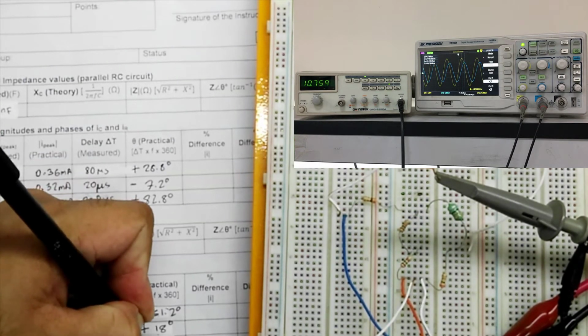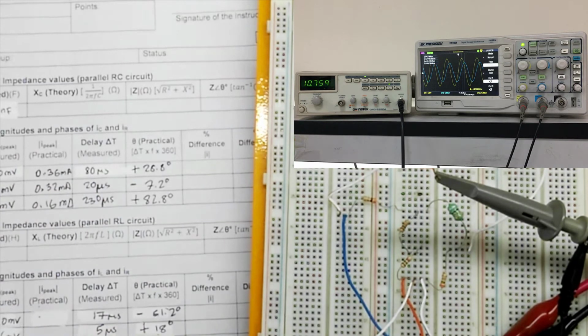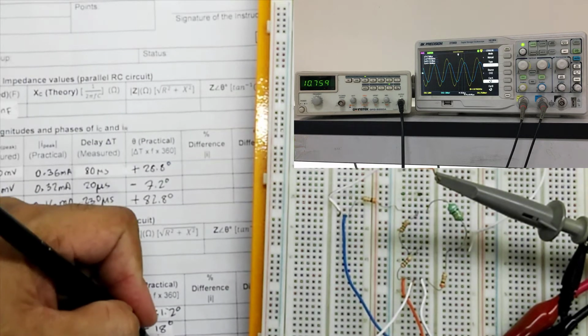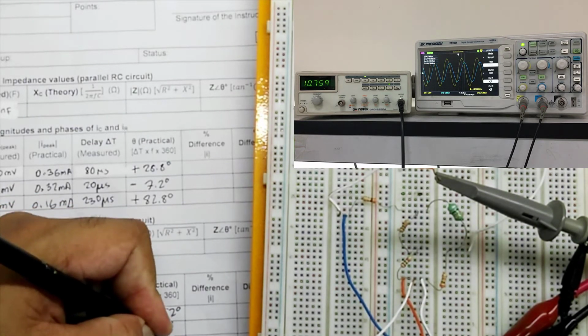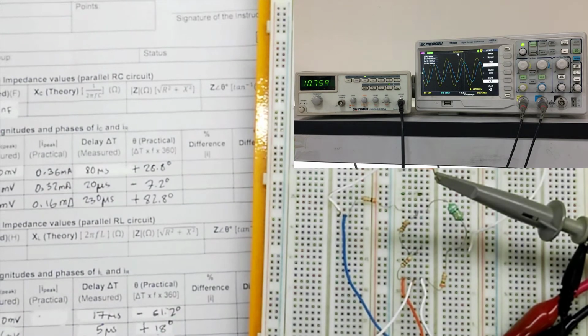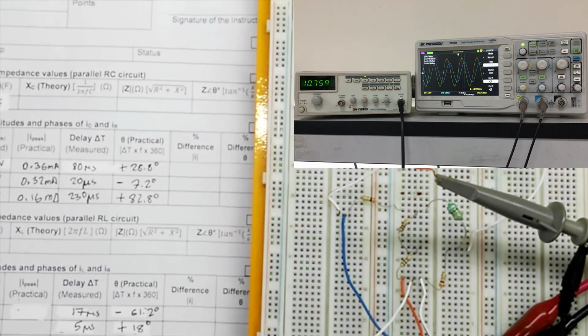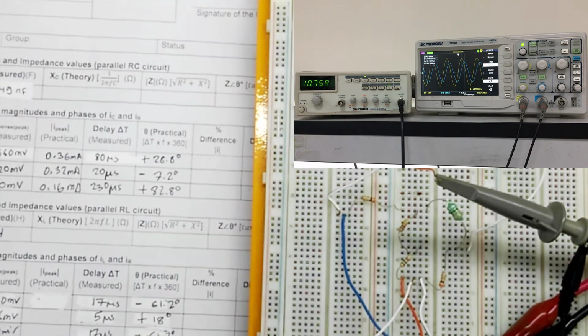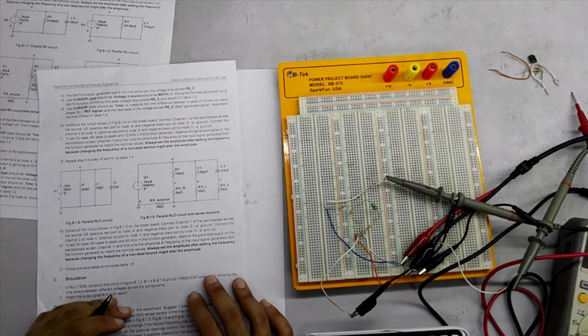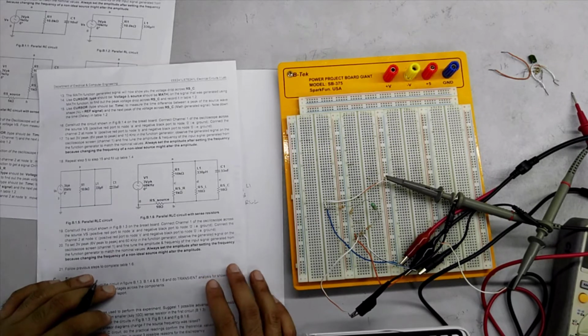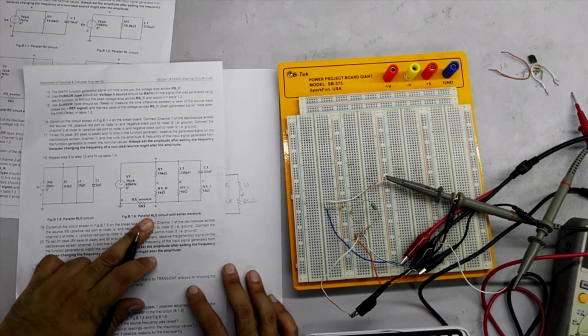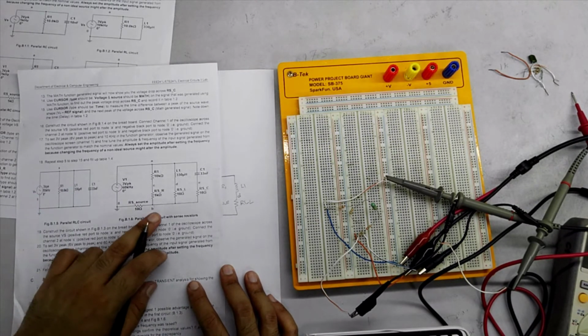The symbol is minus because of lagging, and you see that for 17 microsecond we have 61.2 degree as calculated before. So we have calculated all the necessary readings for our parallel RL circuit. For our third experiment, parallel RLC circuit, we will use the same modification that we used for the parallel RL